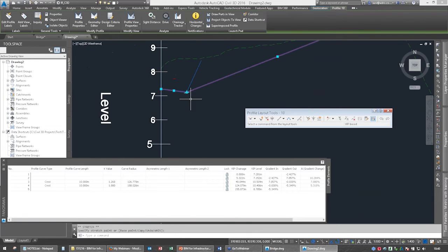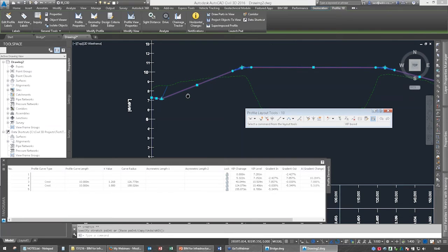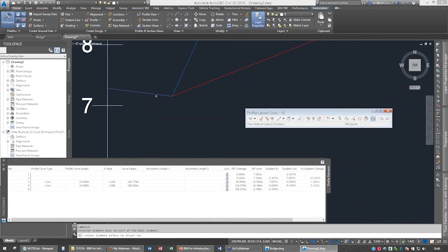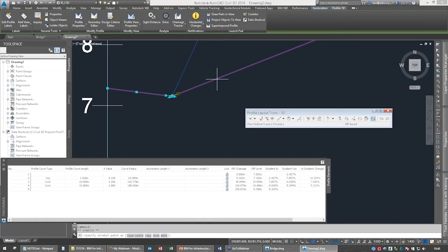That's actually not quite the road, and then put a vertical curve in there. So I'll just stick a circular curve between that point and that point, and maybe I should extend it a bit further out, and we'll just type in the values. I'll just stick a small one in for now, and then we'll have a look at how big I can take that. Tell me object snaps off.